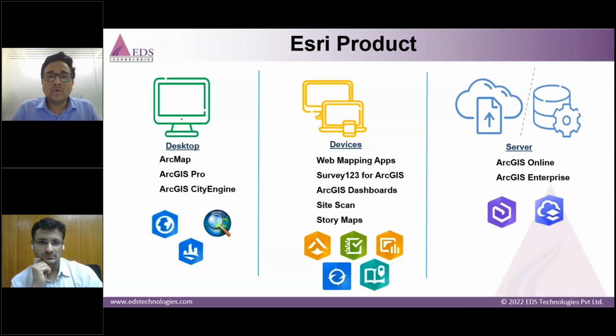So what I need to do, I just create a survey form. That's it. Anyone who has this mobile application, Survey123, just enters the credentials which I provided to them, and accesses that form. He goes to the ground and captures all those data, any data sets. If you want to attach any document like a PDF or Word file, he can attach that. If you want to capture an image, he can also click an image. That image will also be geotagged.